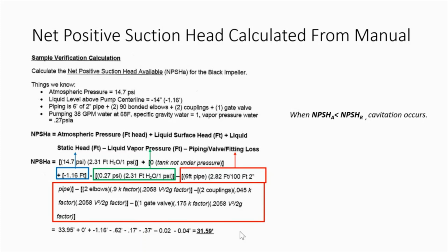All right. So whenever you say a head, make sure what head it is. Meaning the same centrifugal pump can push the water 31 feet out. But if you use a heavy fluid, let's say tar, definitely it's not going to be able to push it 31 feet. It's going to be much lower. So whenever you are defining the pressure with the height parameter, you definitely define what fluid you're using as well.